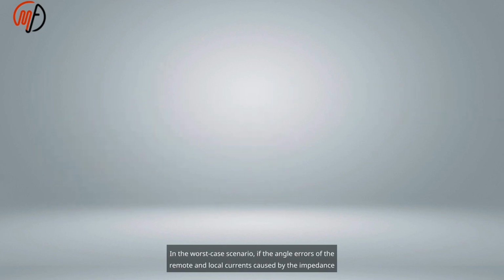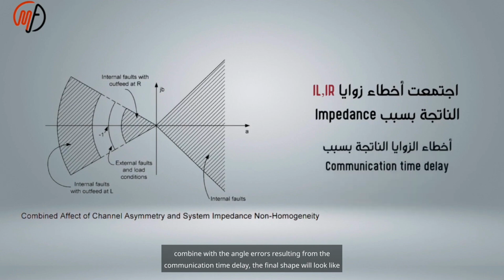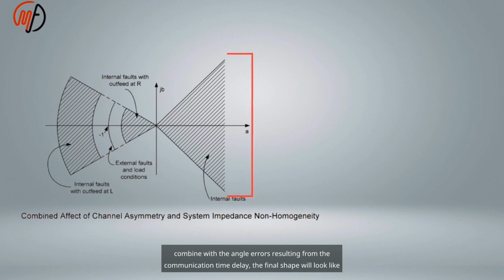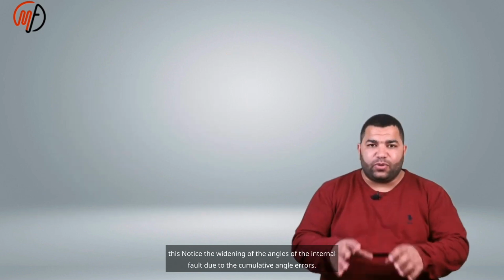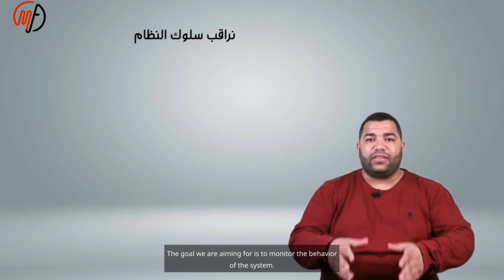In the worst case scenario, if the angle errors of the remote and local currents caused by the impedance combine with the angle errors resulting from the communication time delay, the final shape will look like this. Notice the widening of the angles of the internal fault due to the cumulative angle errors. The goal we are aiming for is to monitor the behavior of the system.